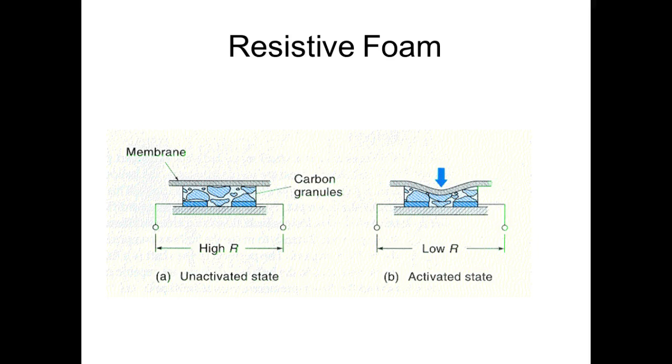So sometimes we like to enclose the robot, the big robot, inside a big fenced area, right? Understand? But sometimes you can't do that. Sometimes the robot can't be in that. I think we was looking at one for Amazon, and they have a big FANUC robot, and they could not enclose that thing because of the way things come into the cell and the way things leave the cell. So we use these a lot. These things are very, very popular. In robotics, they call them pressure mats, and that's exactly what they are.